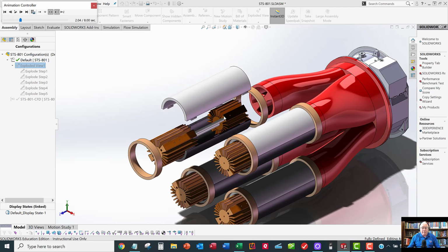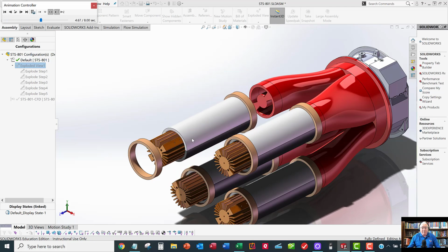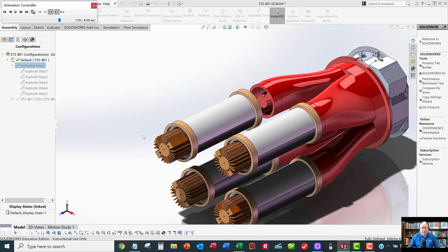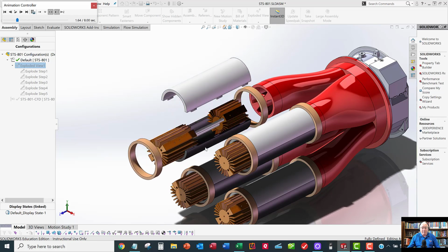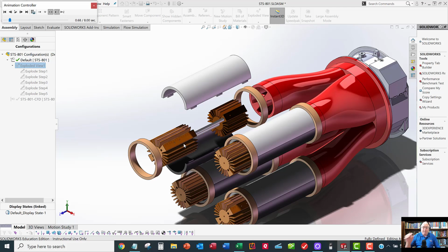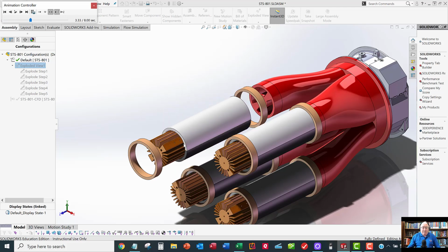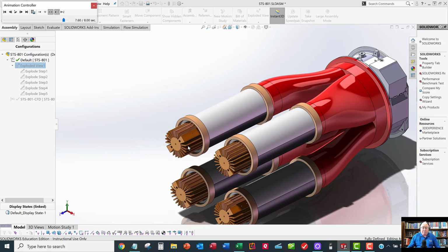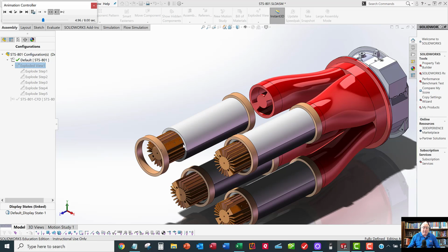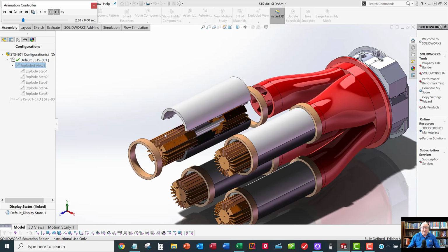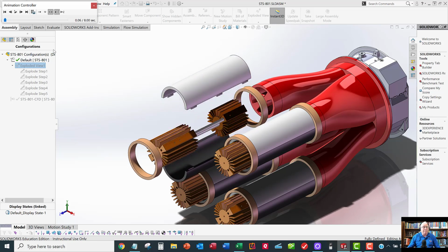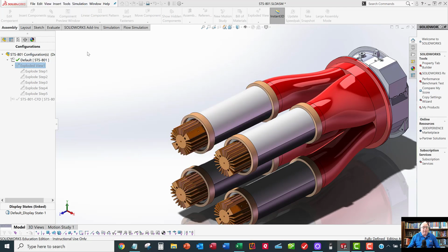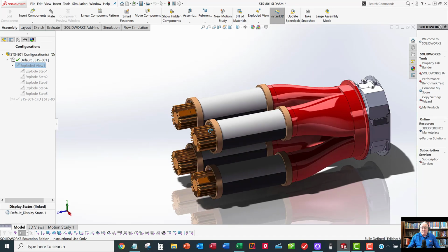We're trying to get the air flowing over these heat sinks and heat pipes to extract the heat. There's a big hot plate that mounts to the front face of all of these heat sinks, and we're trying to get the heat out of there. We're going to use a combination of conduction through the heat sinks and phase change through those heat pipes, and also forced convection, to get the heat out of the heat sinks and into the air and away from the hot plate. Alright, so maybe we'll stop that. Again, this is the manufacturing model.